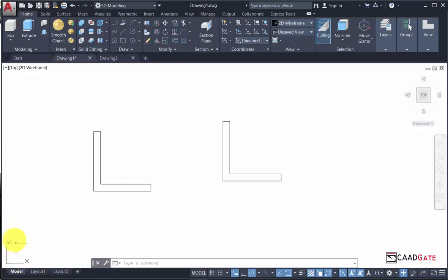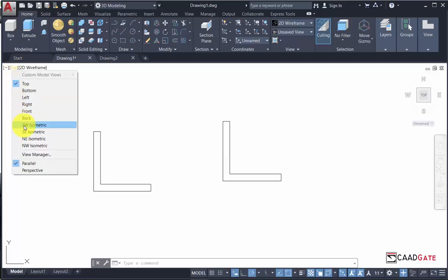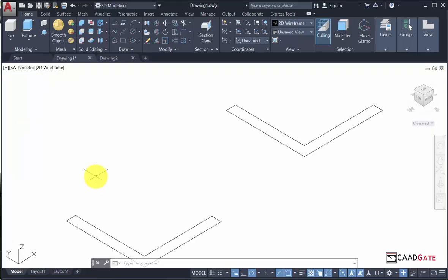This gives us the impression that okay, we are working with 2D. So now we are going to switch to 3D. Go to the view controls here and go southwest isometric. You now see a third axis, the Z-axis. In all instances, Z-axis gives you the depth.